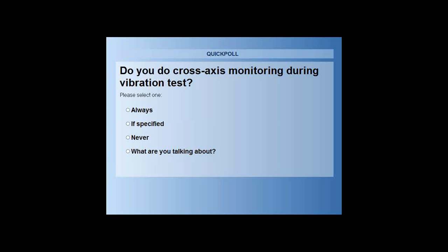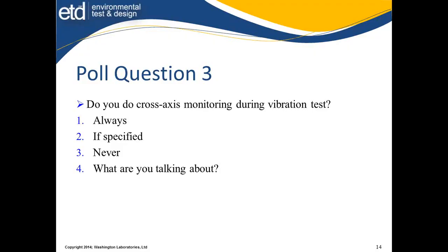For instance, a high cross-axis test for the Y parameter, when we're trying to do the X parameter, could indicate that a failure or a pass could be related to some cross-axis event. Now, we know we're going to rotate it to the other event anyway, but it may not be something we see. And when people start analyzing their failure mode, if it fails in the X-axis, and they don't know that they were having a cross-axis problem in the Y, they don't go looking for things that could have happened that way. They start fixing a problem based on what it appears to be. So consider doing these things.